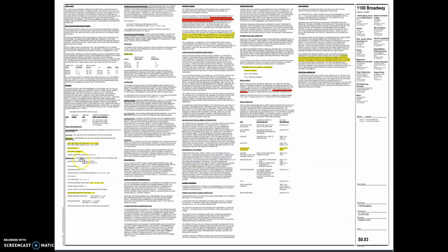We'll go to the second page here, and we'll start to look into the actual design criteria. Usually it's labeled structural design data or something similar. We have our wind loads, which give us our wind speed, risk category, exposure, and then our seismic loads give us risk category, importance factor, spectral response, the SDS, SD1, and then the response modification coefficient R. What's not on here is the CD factor, which is typically used if we're only given inelastic, that we can then use that CD factor to get to the elastic, or if they're giving us elastic, we can use the CD to get to inelastic. Either way, we would take all these things and write them down in our design criteria worksheet, and this is what we use to get our wind loads when we do our wind load analysis, so we can start doing deflection runs.